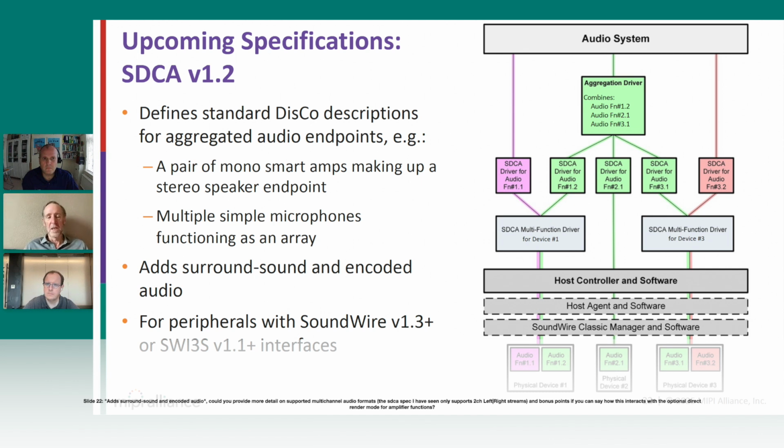And indeed, as John said, when you want to do these render direct or capture direct, you're requiring now that the host side actually has intimate knowledge of exactly what's going on. Where is a microphone? Where is it pointed? What are its capabilities? Where are the speakers? How are they combined? If I've got a two-way speaker, which amplifiers are driving the woofer?